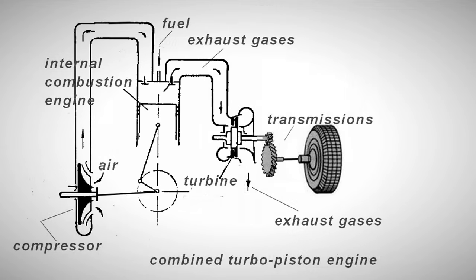This resulted in a combined gas turbine unit with a piston gas generator, combining the positive qualities of an internal combustion engine and a gas turbine. High temperatures, unsuitable for a gas turbine, were handled by the diesel engine, and its power was expended on the compressor. The low-pressure, high-volume region was handled by the gas turbine, which had advantages over the diesel engine in this regard.